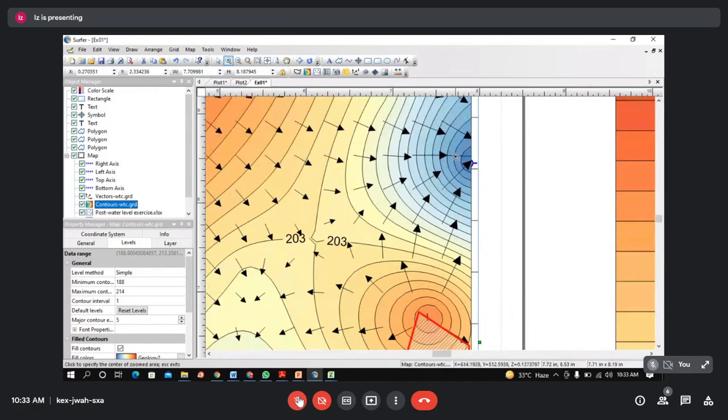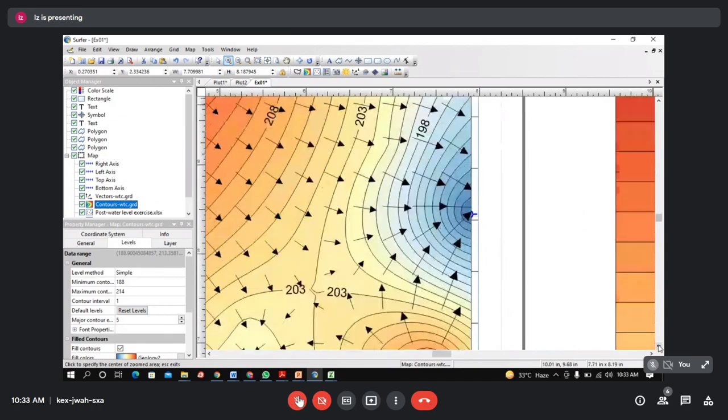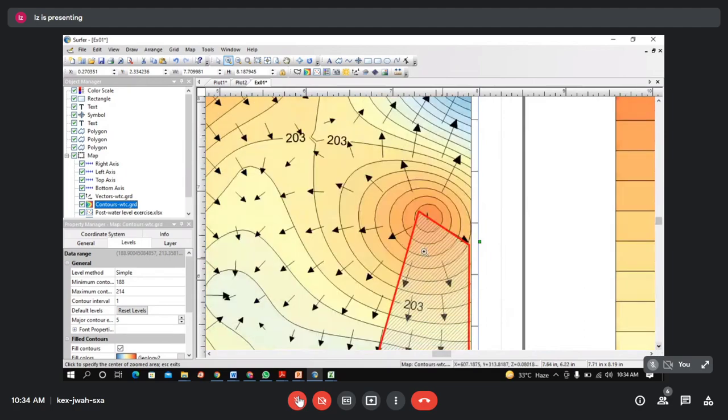And there is an opposite character in this neighborhood. These would be the recharge area and the discharge area. This will be the recharge area because the contour pattern is such that the highest contour is in the middle of the circle, right? In the middle of this concentric area, the middle contour is greater, while in the other the middle contour is smallest. So this will be the discharge area, or this is the cone of depression, right? And this is the mound. This is the recharge area.